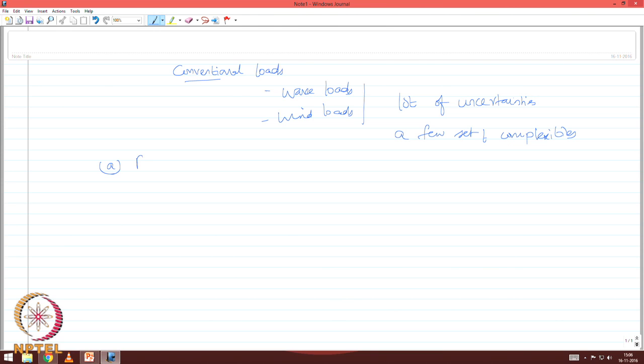What could be the fundamental reason that these loads, though being conventional and well established in the literature, cannot be estimated with the greatest possible accuracy by eliminating the probability of exceedance of these forces? The foremost issue which circumscribes the calculation of these in probabilistic terms is return period. So, let us ask a question, what do we understand by return period?